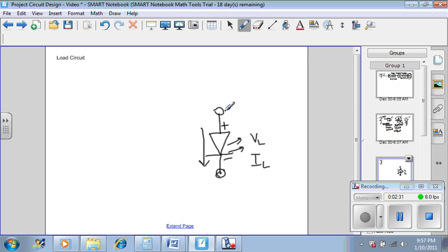Now this LED, from the data sheet, usually since the LED is a diode, you probably find something on the data sheet called a forward voltage, like forward bias. I learned from one data sheet that the forward bias of a typical green LED diode is about 1.7 volts.